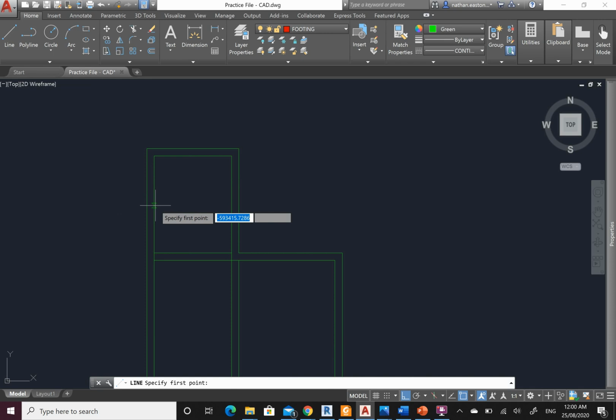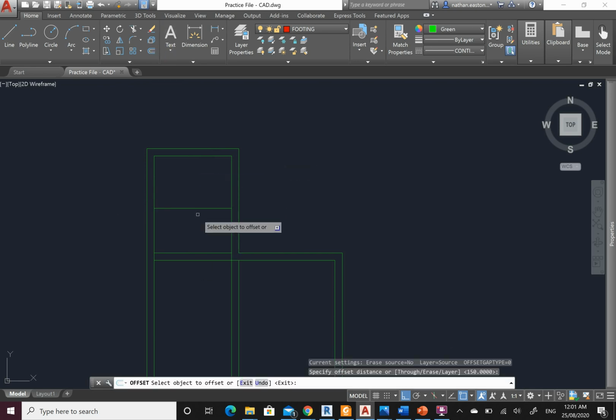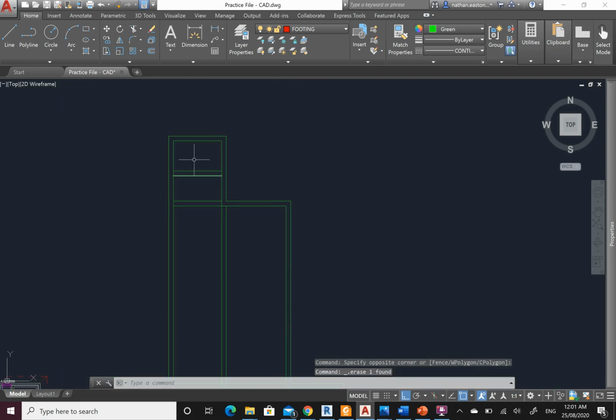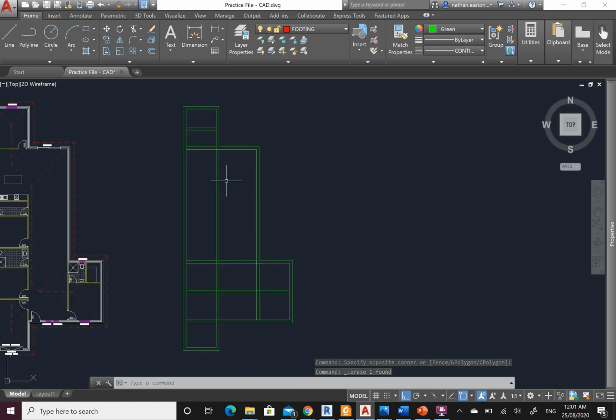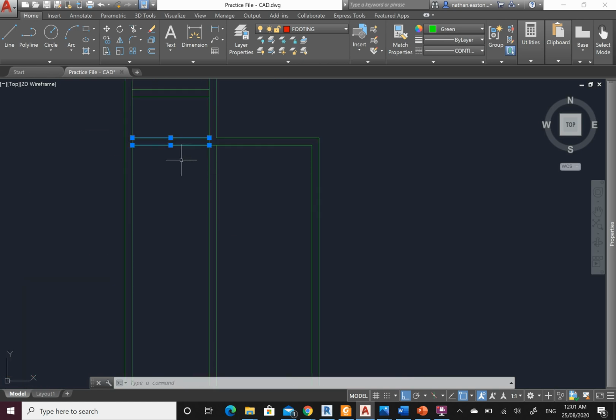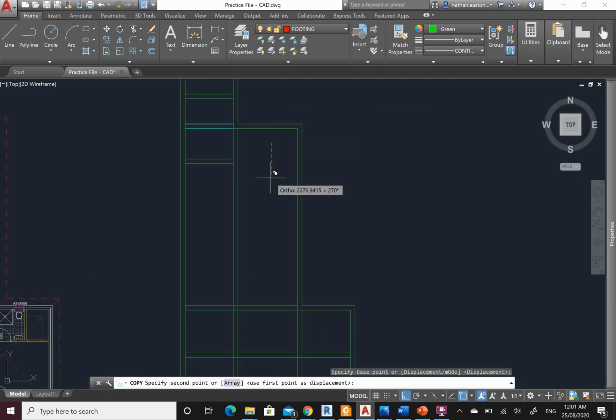If we were to do it on software, we would probably get away with it and we wouldn't have to. But for the standards, we don't have a choice. It costs a bit more. Again, it's conservative, but that's okay. So we delete this one. We've got a stupid, annoying footing there, but that's all right, we haven't got a choice. Now, let's copy these. Copy. First footing in has to be 4 meters.